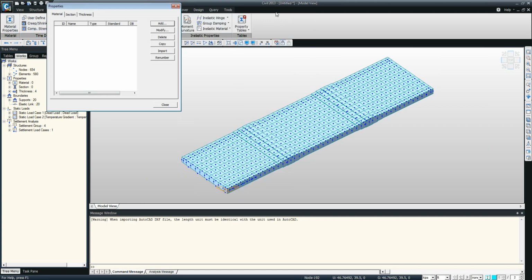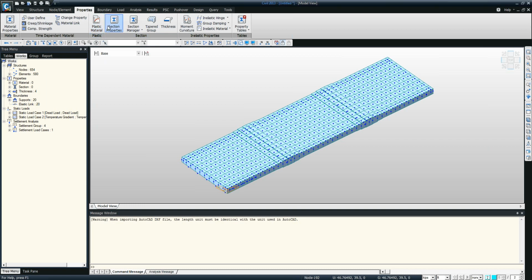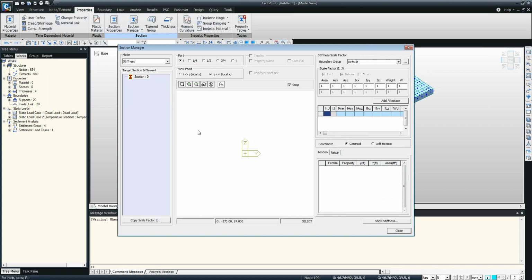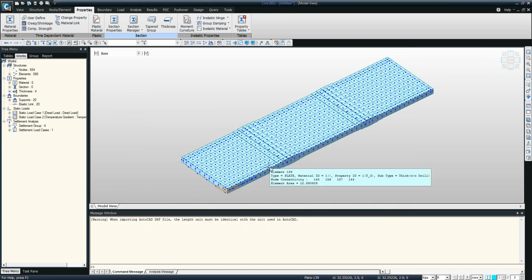It's very simple to model this behavior in Midas Civil. What we can do is, we can go to section manager and reinforcement here, and when I have the composite cross section, I'm going to show it to you later, I can check on the cracked section properties, and then the program will consider only the steel girder and the reinforcement when it computes the stiffness at the negative moment zone. So this type of analysis scheme can be modeled in Midas Civil. I hope I answered your question, Russell, and I'm going to show it to you later on when we do the modeling. Let's take one more question.